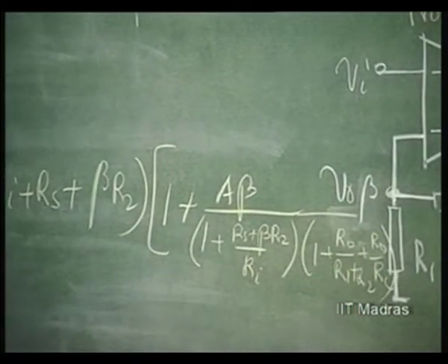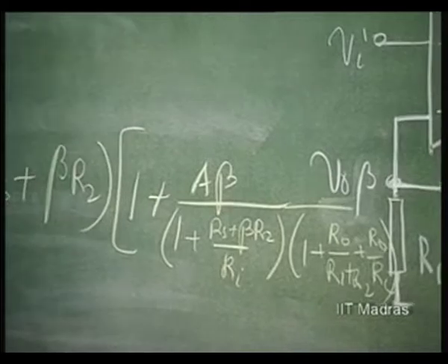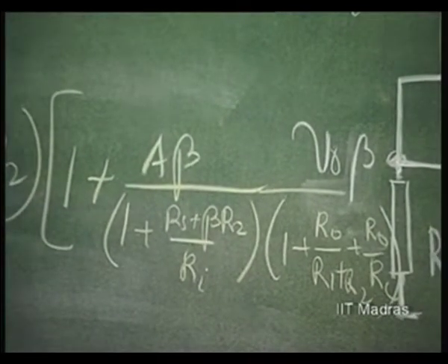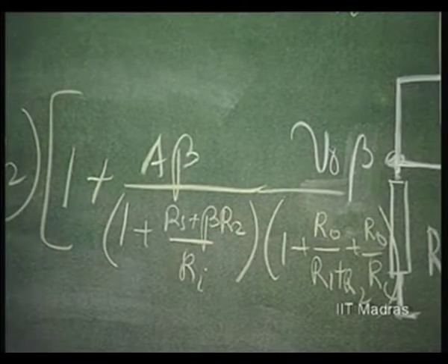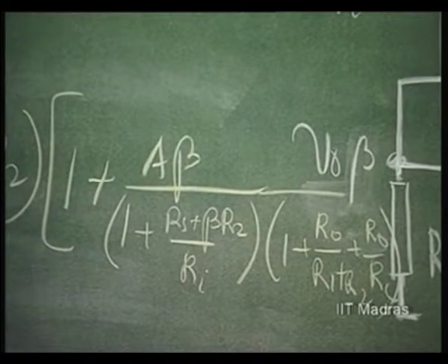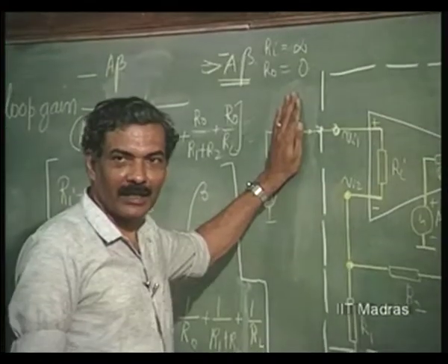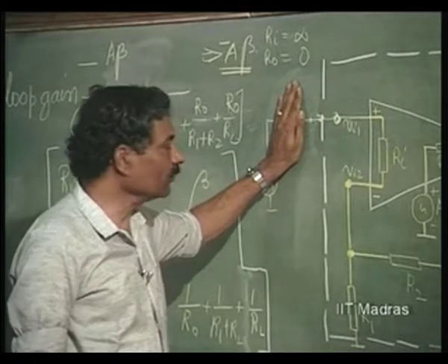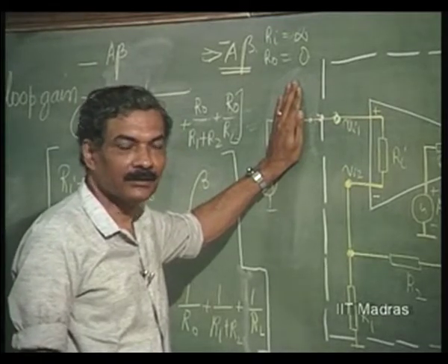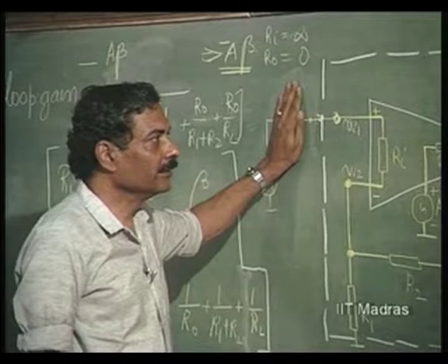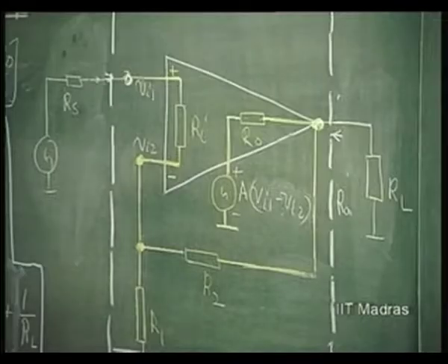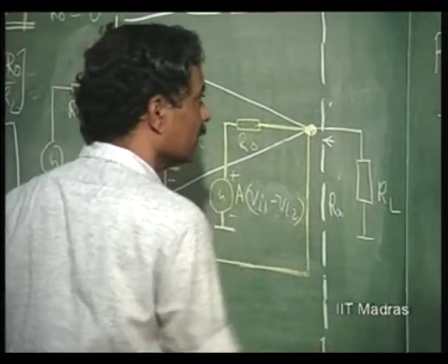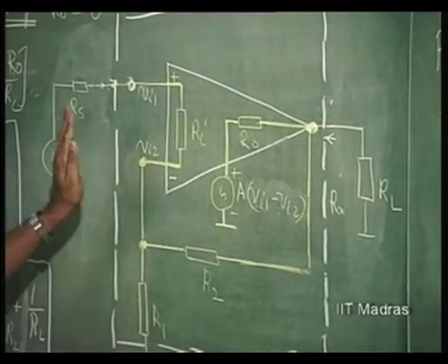That is actually the input impedance. So, you can see that it is increasing very much. Input impedance seen from this side, which is going to include Rs, right. So, if you remove Rs, it will be input impedance without Rs, right. From this you subtract Rs, okay, that is the actual input impedance seen from here. Okay. So, Rin of the amplifier really speaking is this. Okay. So, this is including Rs.